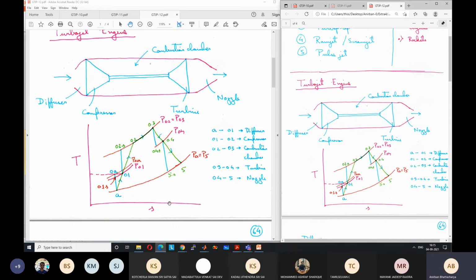That will occur if the nozzle operates at choked condition. So can the aircraft fly at supersonic velocity with the nozzle at choked condition? No, sir. We have to use convergent divergent for that.